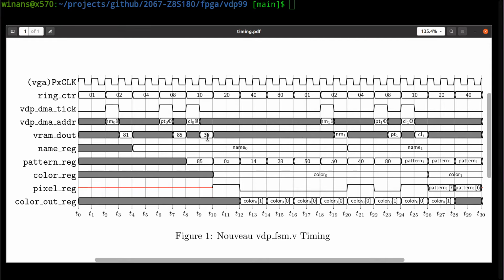Look it up, give me the value out of there. This thing gets latched into this register, and this register down here, based on whether this is a 1 or a 0, will be taken and sent out on the 4-bit output that comes out of the VDP. That tells me which color I'm supposed to have. It'll either be the most significant 4 bits of the color register value or the least significant 4 bits.